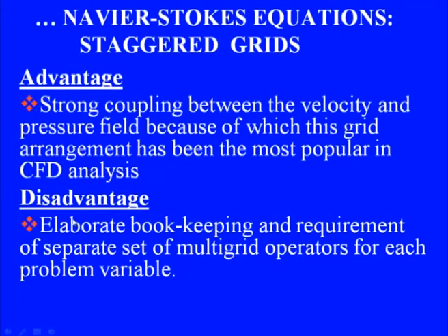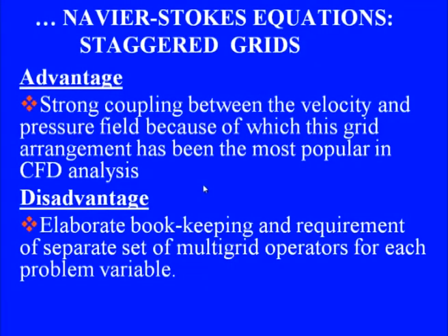But notwithstanding this disadvantage of elaborate bookkeeping and having separate sets of operators, the advantage which is offered is a very strong motivation, and even today staggered grids are used in preference to co-located grids in the context of structured finite difference or finite volume analysis.